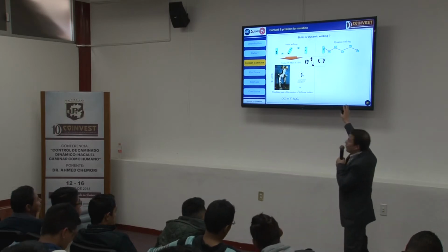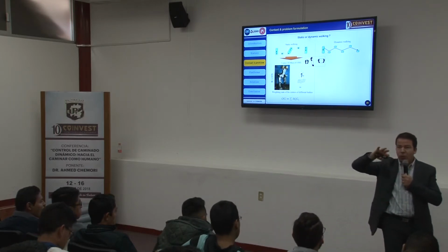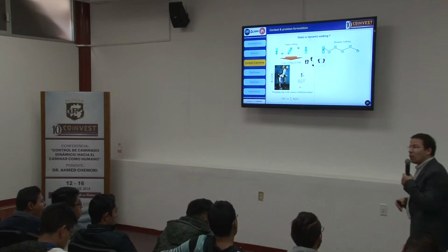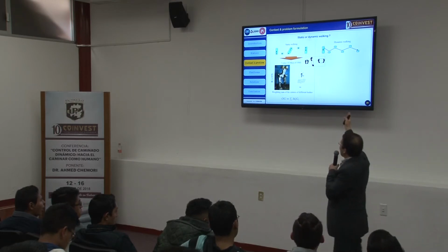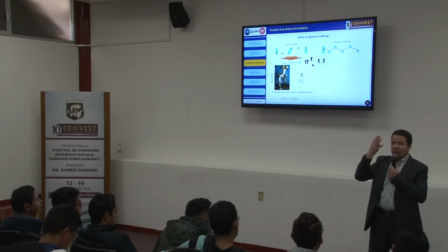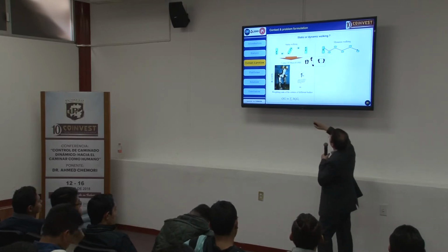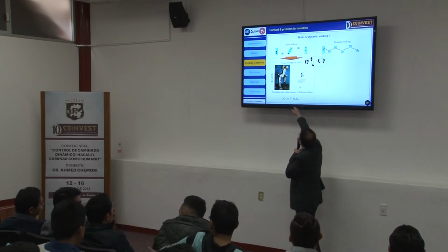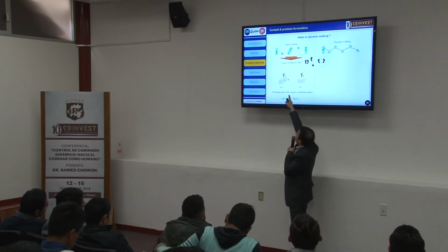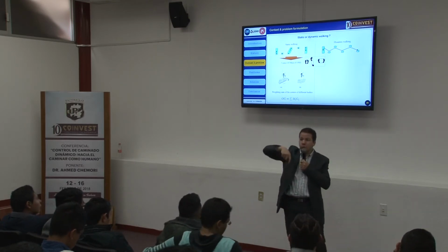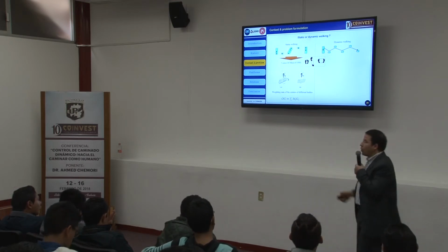But this kind of walking is much better than the static walking. Why? Because the speed can be higher, the dynamics can be better, and the walking can be more performant. Now, here, as I said before, the idea is to compute what we call the center of mass, and we compute the projection, and we keep it inside the polygon of support.